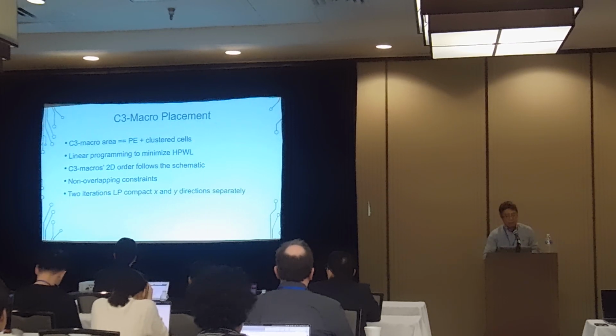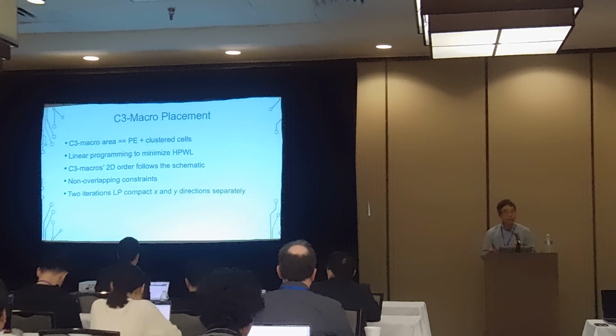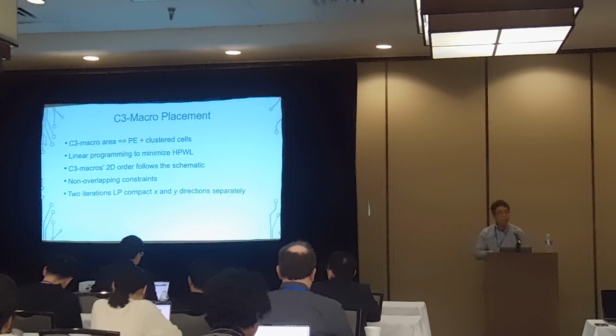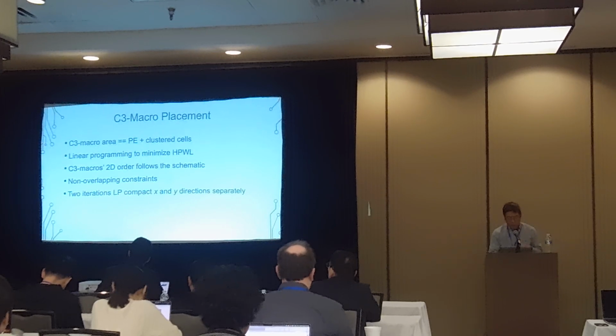Okay. And at this moment, when we do this placement, we leverage the regularity because this is a 2D array. So the order is pretty much decided. We just follow the order of the schematic. And so then we can easily apply linear programming instead of nonlinear programming to solve this problem. And actually we use two passes of linear programming. I will skip some details. Actually this work was published in ICCAD last year, so there are some details I skip.